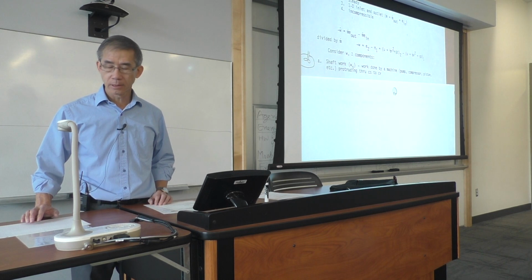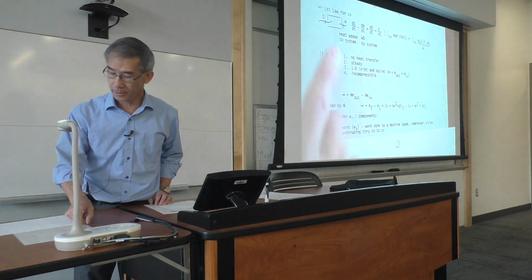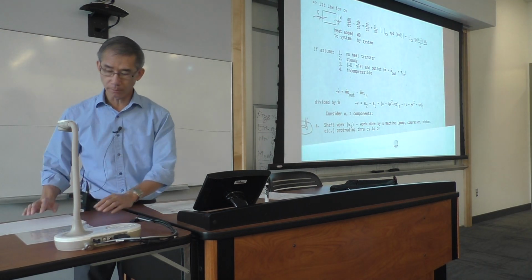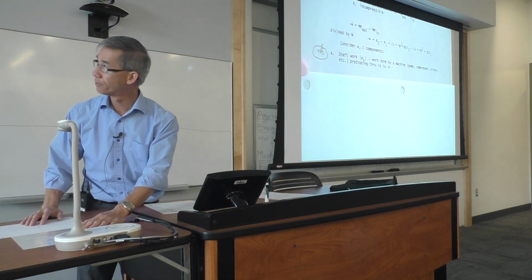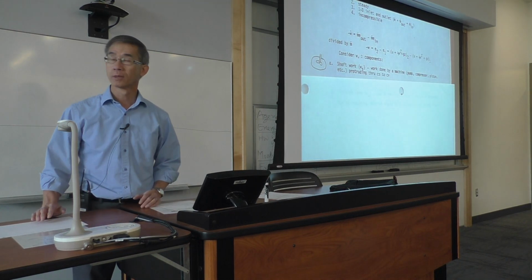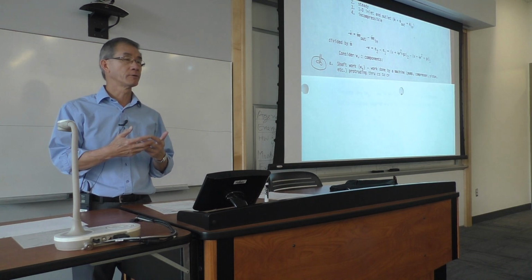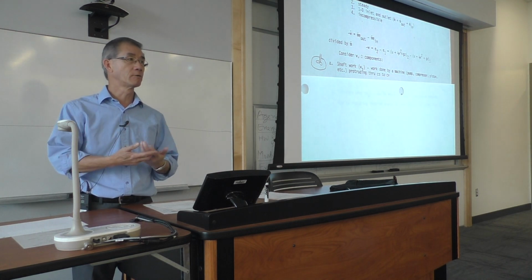The work into my control volume, like defined in here, which can be a turbine or a pump, consists of two pieces. The first one is obvious, the shaft work. If it's a pump, I'm running it with a motor, and the electrical power to run the pump is added to the fluid.